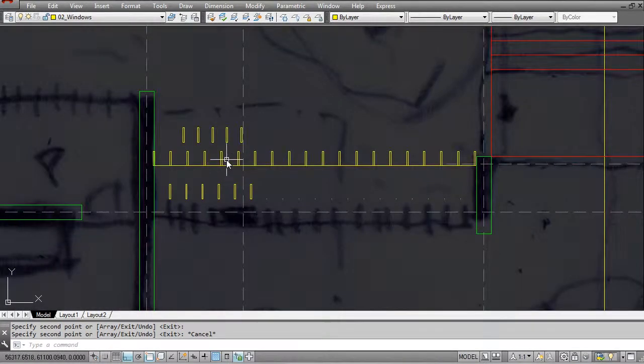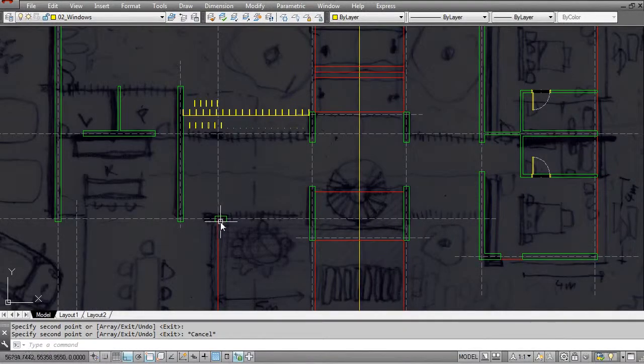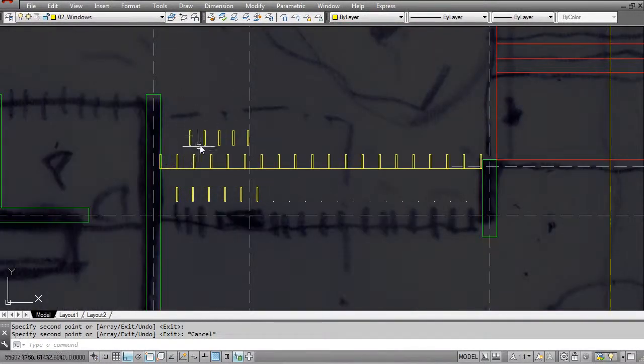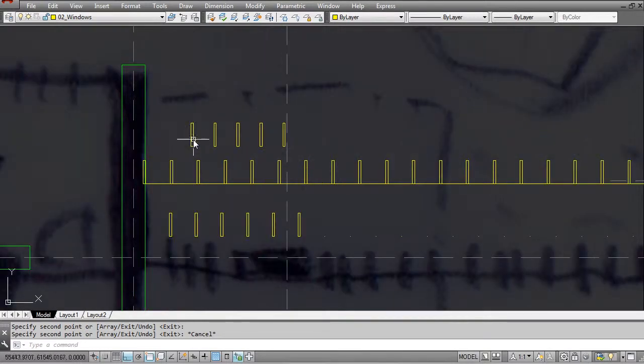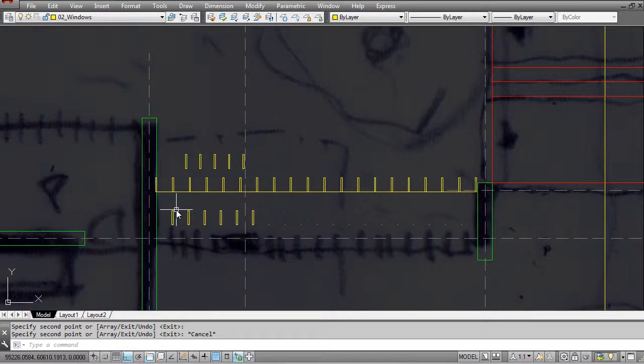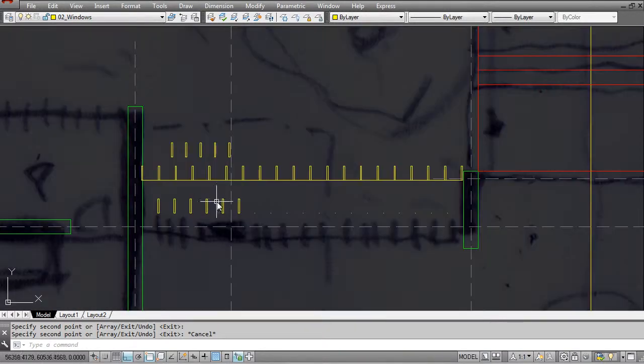And also remember that you can use the block technique to actually turn each one of these objects into a block. For example, if you have a complex screen detail with a pivot point if the screen moves, or any type of window detail that you then want to add detail to later, always remember that you can, in the sketch design phase, create a simple square, turn it into a block, and much later come back and then just edit one of those, add more detail, and all your frames in your entire building will update. So that is definitely helpful when you create all of your windows.